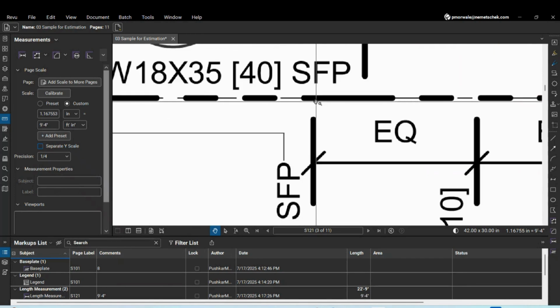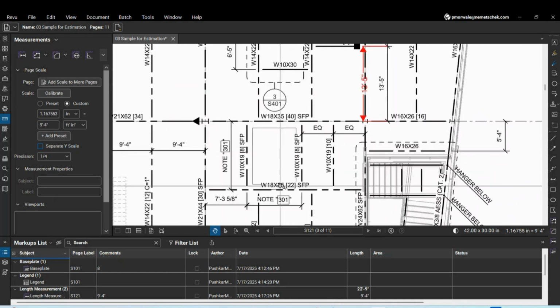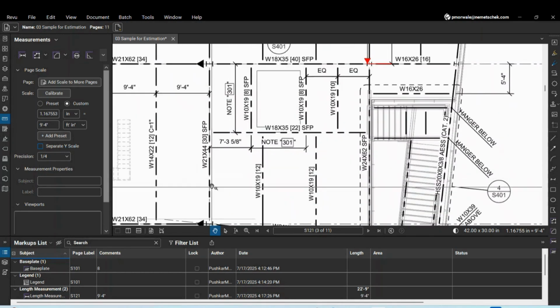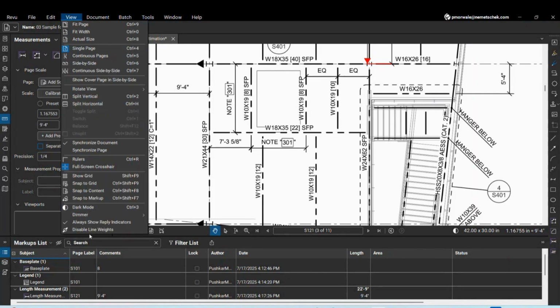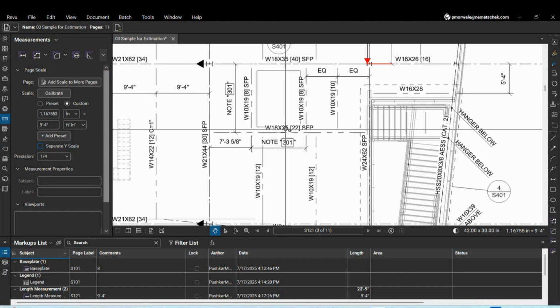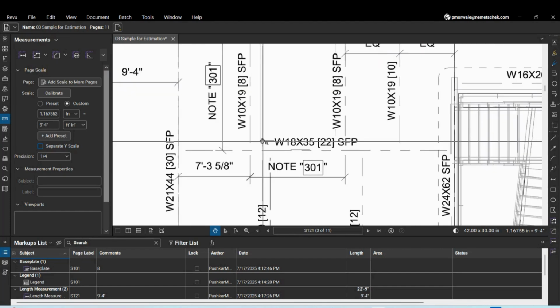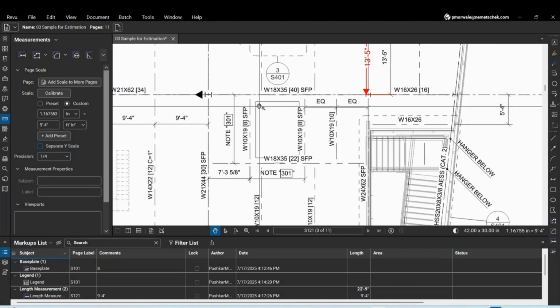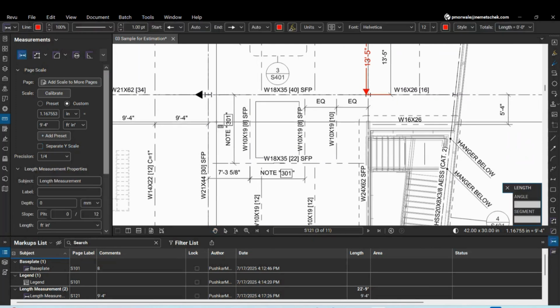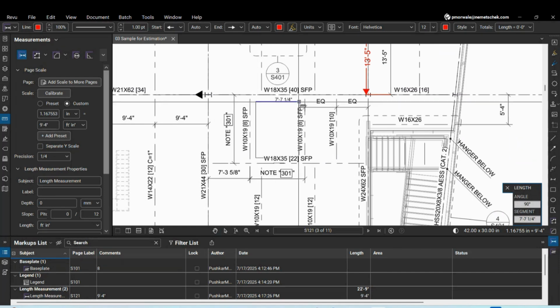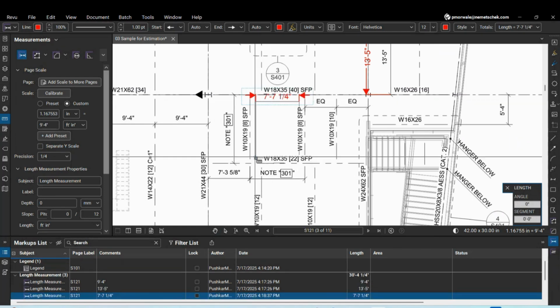If you want to pinpoint a specific point, it may be difficult if the line weights are enabled. The line weight generally comes along with the drawing from whichever drawing application you are using. So Bluebeam offers you to disable line weight so that you get sharper endpoints or intersection points. Now let us try to find out the length and width of this particular cutout.